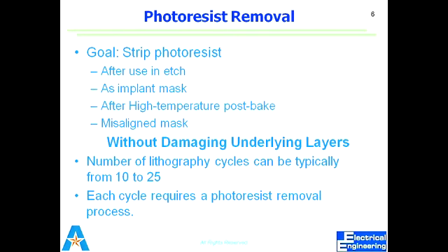But it has limitations: only a thin layer, and secondly only metallic layers. So it's not a topic of discussion for today, but you will discuss it in detail later on. Okay, but you know that whenever we do etching, etching is always done after photolithography. That's what I was trying to tell you. So after the etching process, you need to make sure that there are no photoresist residues.